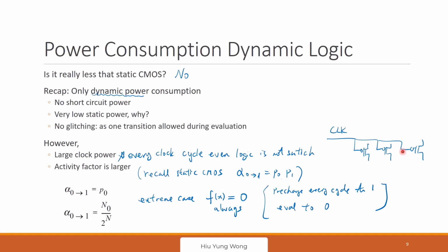Yeah, I got it. Is there any formula or any other way we can consider this equation so that we can design the clock, or is it random? Not random. You just go back to what you learned: RC delay. How much time you need to drive, or how much time you need to propagate the signal. This is a transmission line. You go back to the capacitance and resistance of your clock, and how many gate capacitances you need to drive, and then calculate it, and it needs to be smaller than half of the period.